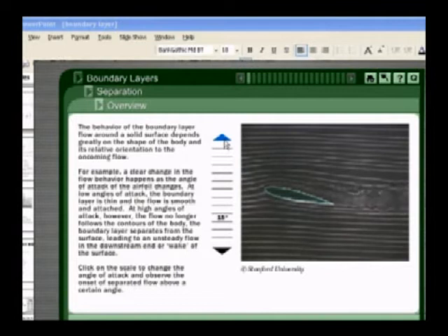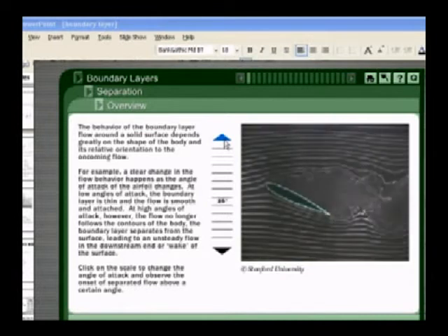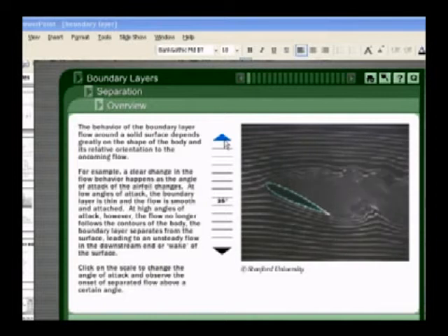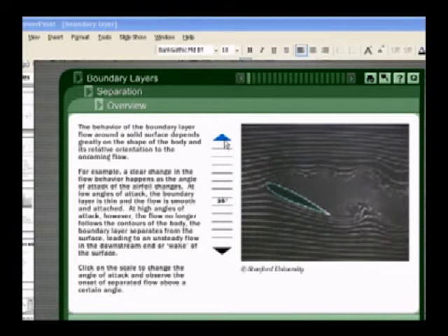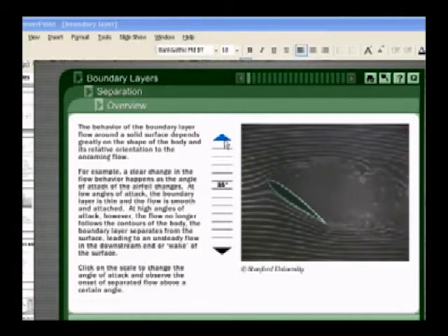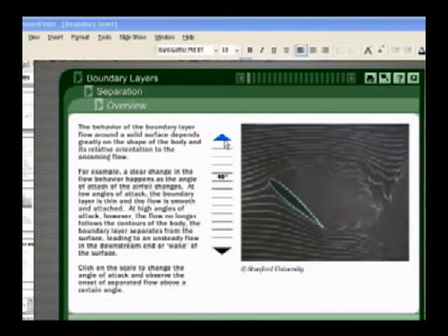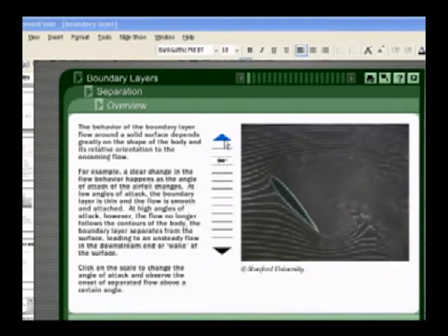The boundary layer is said to be separated, and as we have more angle of attack, we have more unsteady flow on the downstream side. Though we have a steady flow over this aerofoil, at the back of the aerofoil, due to separation, we have a separated fluid flow which causes very huge resistance. So at different angles you can visualize this.